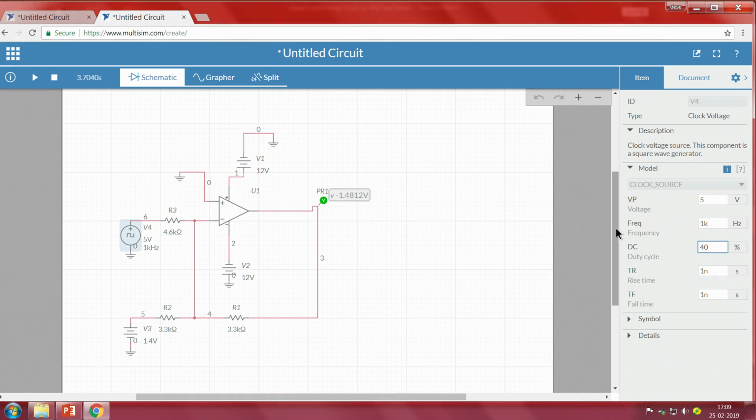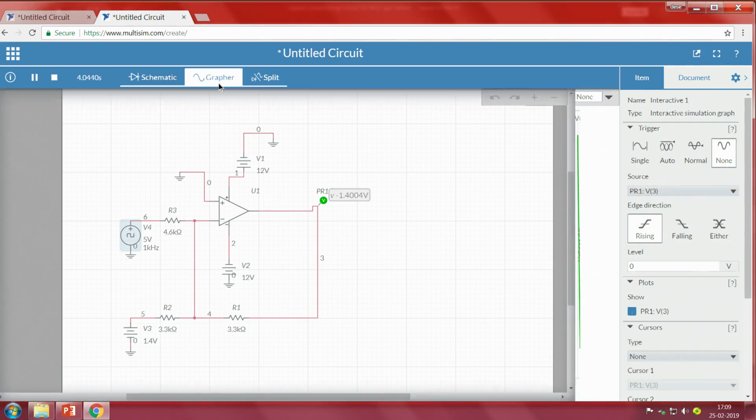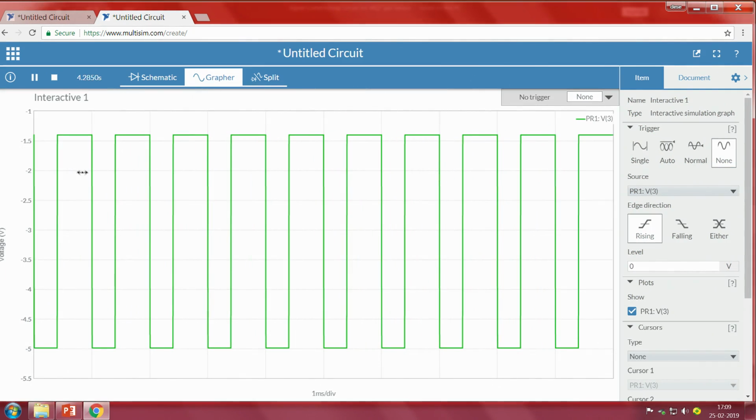That is why you can see why this kind of circuit becomes important, having a reference voltage, so that you can manipulate your output between two levels of voltage rather than just going from 0 to 5 volts. So here I have set the duty cycle and we have given the input voltage. This is the on and off time.